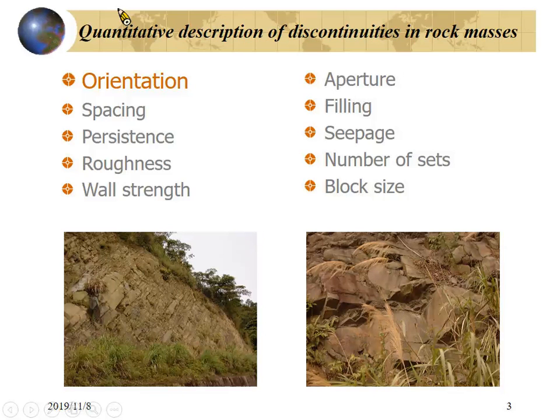Do you still remember? I teach you about 2.1. Start from orientation, spacing, persistence, roughness, wall strength, aperture, filling, seepage, number of sets, joint sets, and block size. Okay? Right now, I want to talk more about orientation.